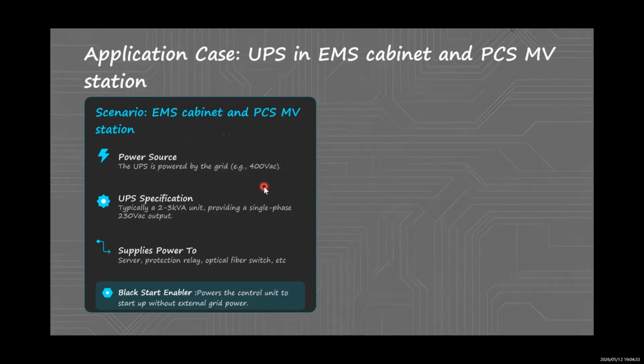The next application case is UPS in the EMS cabinet and PCS MV stations. It's an easy application. It will provide backup power to the server, protection relay, and network switch or optical fiber switch.